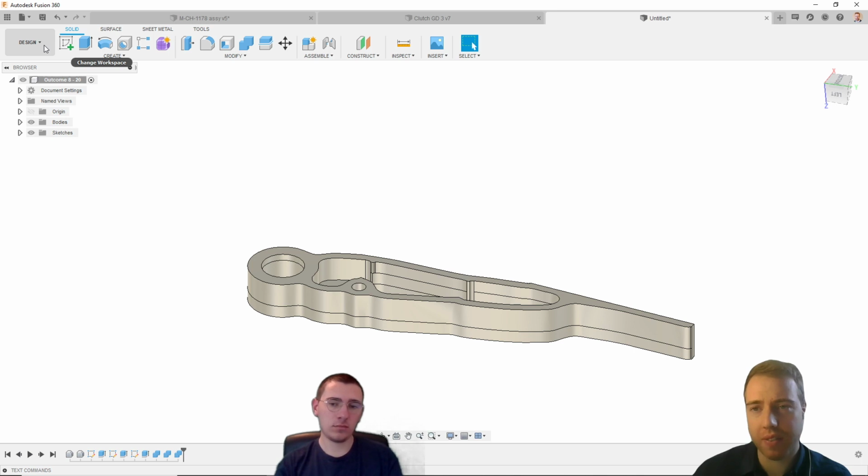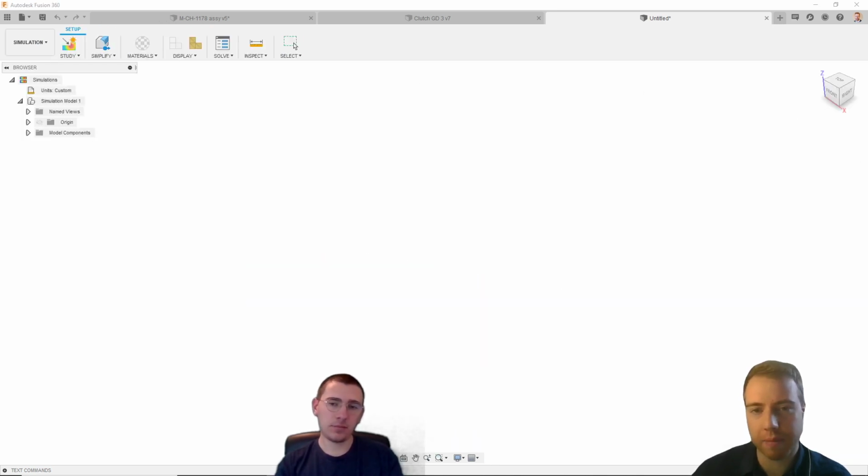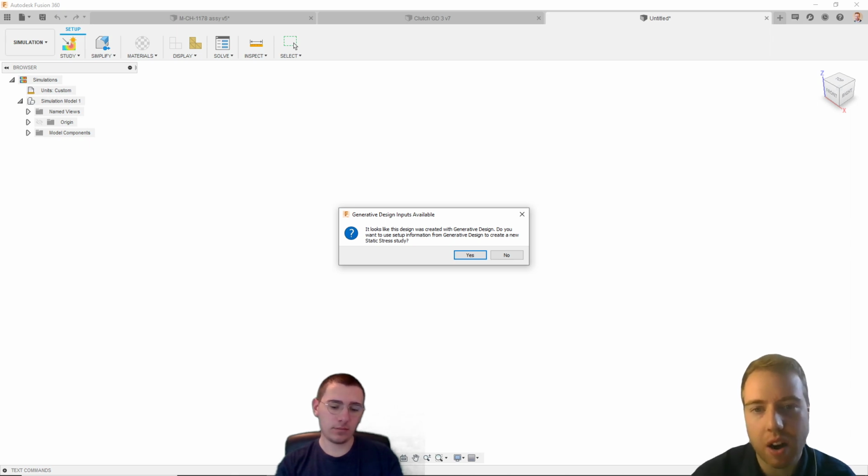So what's going to happen is, if I drop down from my design workspace and go into simulation, it's going to come up with this dialog box here, and this is going to say, looks like the design was created with generative design. Do you want to use the setup information from generative design to create a new static stress study? If I press yes,